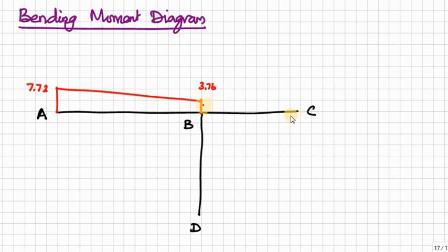Again for BC we have minus 2.90, by convention we have to draw on the upper side, therefore 2.90 here, and this is 0, therefore join. Here also BD, and at B we have minus 0.86, therefore upside. We are standing here, therefore this is upside, and here minus, therefore down 0.43. So join by a straight line. So these are the support moments.